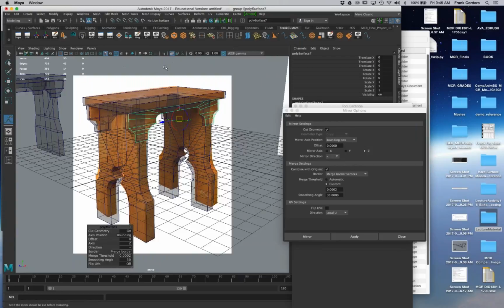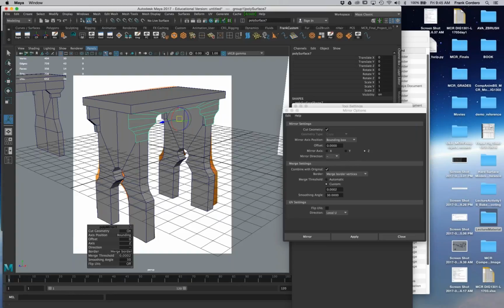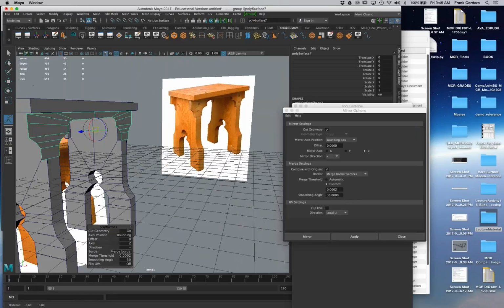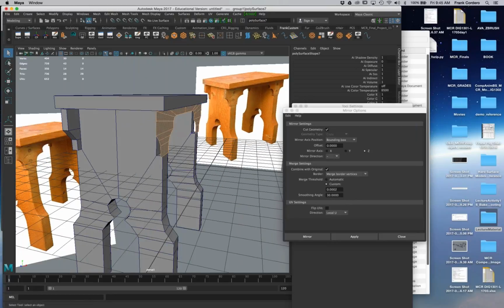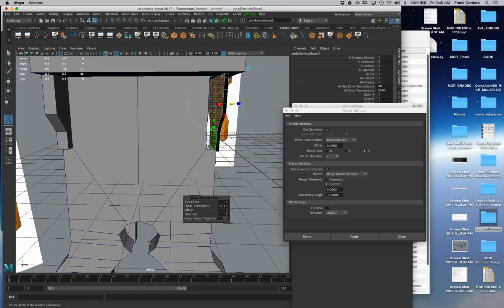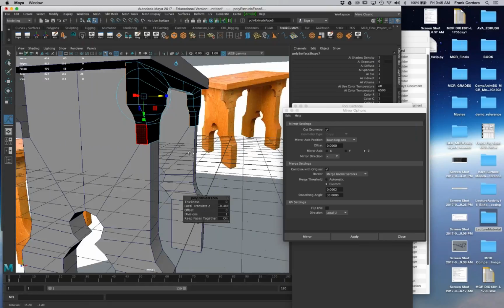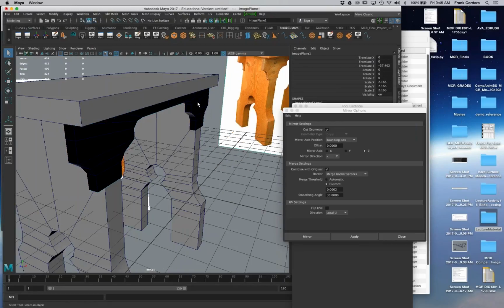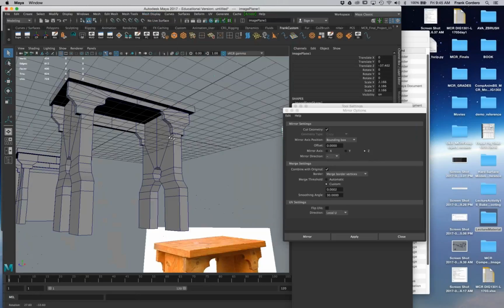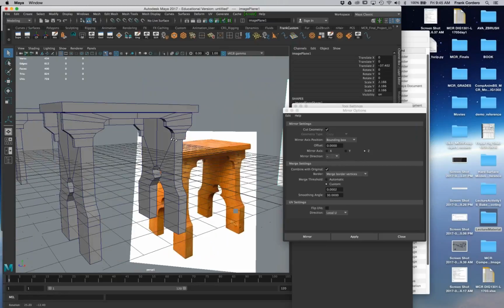And now we can use our blockout. Let me turn this off. And let me go into my second perspective window so you can see this. So that shape is there. And now I'm going to go grab these faces and extrude for depth and thickness. So I'm using my blockouts. I'll even snap, boink, right there. And then I'll reverse the normals. So now this is starting to come together.